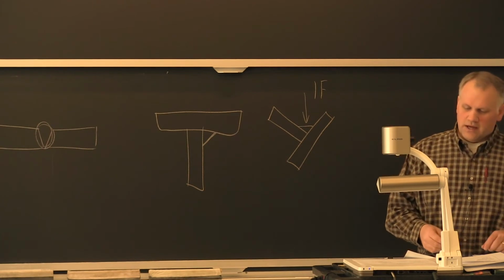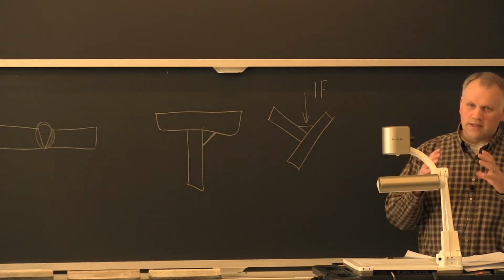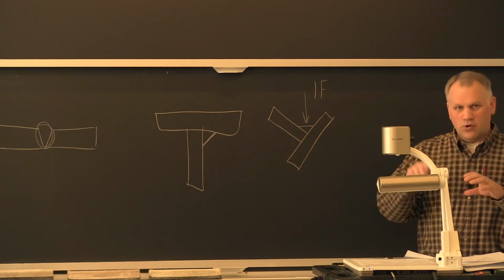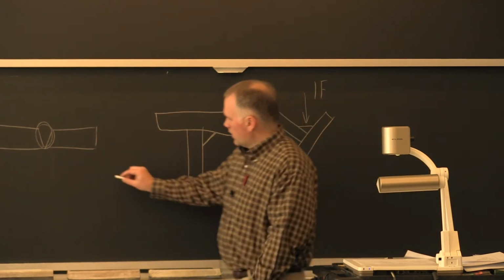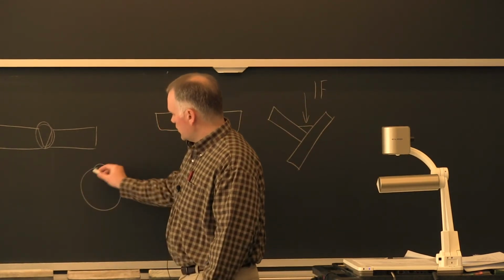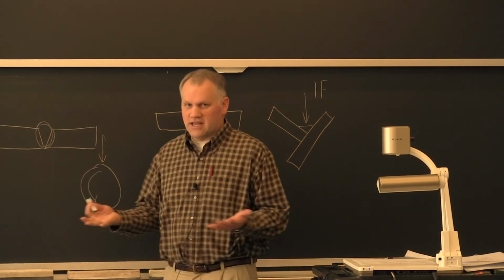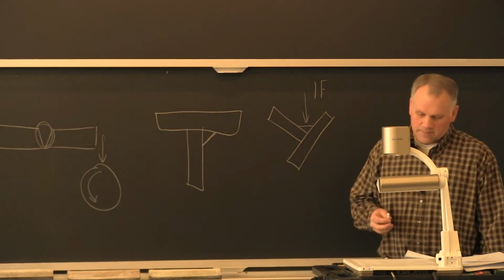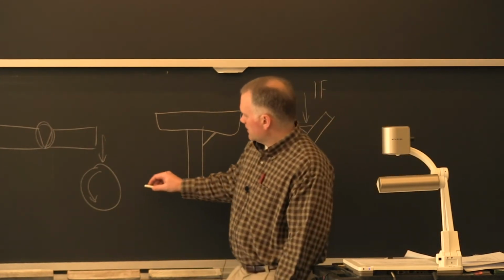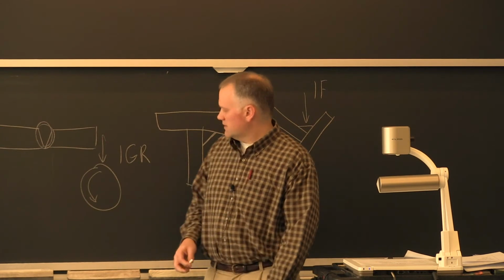So the other positions that you could have are vertical, overhead, and then when you're welding pipe, you can actually rotate that pipe. So if you're welding on a pipe here and you're rotating the pipe and you're just welding from up here, then it's actually in the flat position. You're just rotating the pipe underneath. And so you might have a 1GR, which means it's rotated.